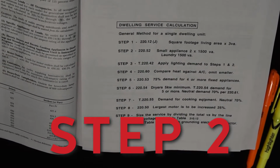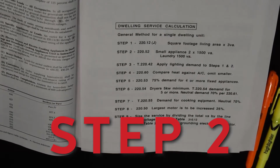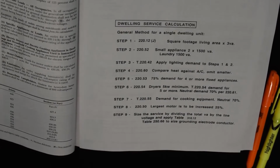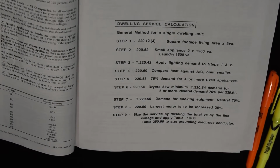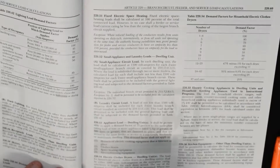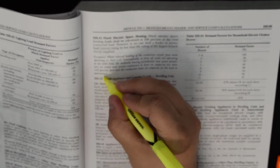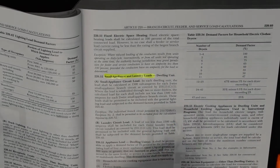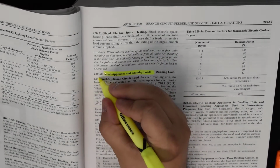Step 2, it says 220.52. It says small appliances, and it tells us in the step-by-step format, 2 of them at 1500 VA, and then a laundry at 1500 VA. So let's look at 220.52. And 220.52 is in 2 steps. We've got the first part, A, then we've got B. So highlight small appliance, and then highlight laundry in the title block.